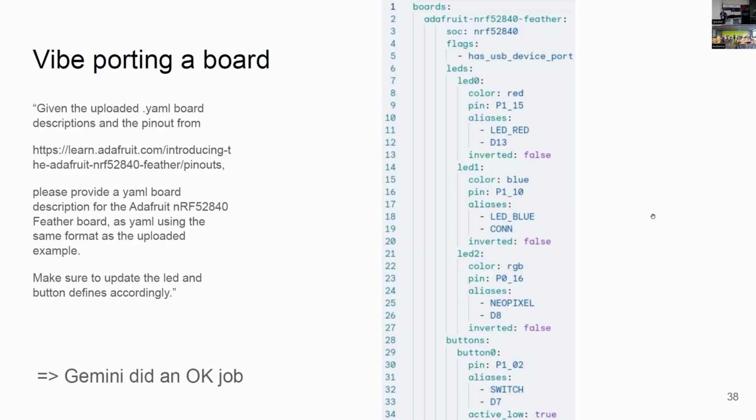And the third question would be, do you intend to also add a validator? For example, for STM, the Cube IDE has a validator, so that hardware designers can actually see if what they design can actually be implemented. But Microchip, for example, doesn't have that. You could end up with a PCB design that can never be used. Obviously a stupid error, but the human will have to carefully check every reference to see which communication can be selected.